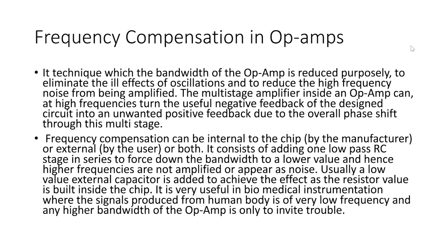Frequency compensation in op-amps. In this technique, the bandwidth of the op-amp is reduced to eliminate the ill effects of oscillations and to keep high frequency noise from being amplified. This technique is used in op-amps to avoid the high frequency noise effects.